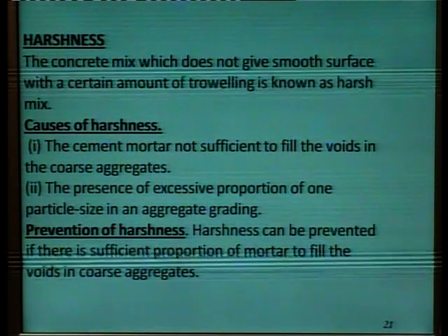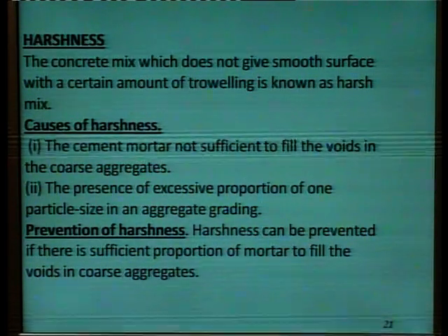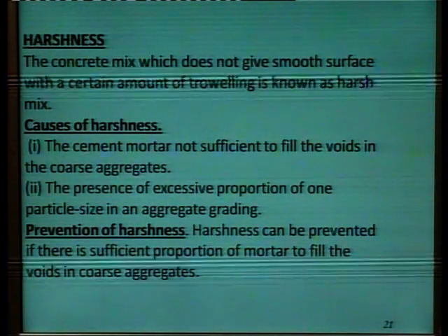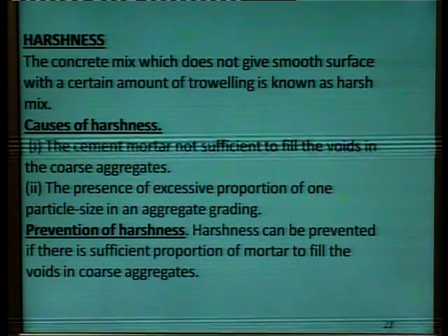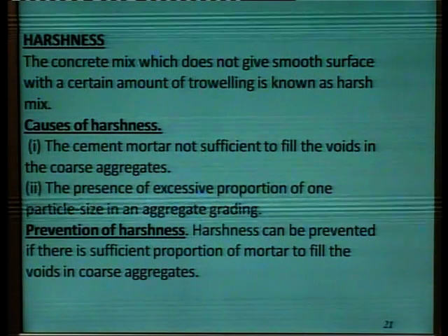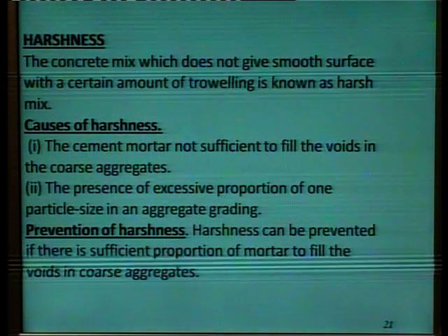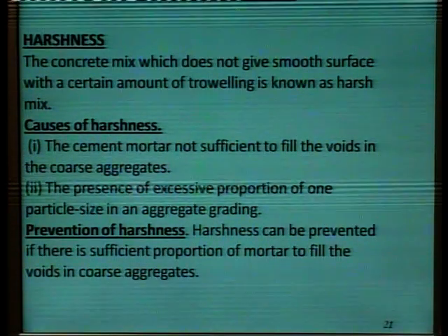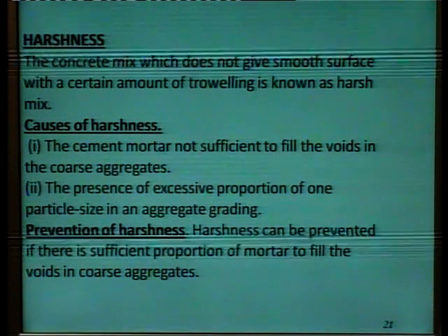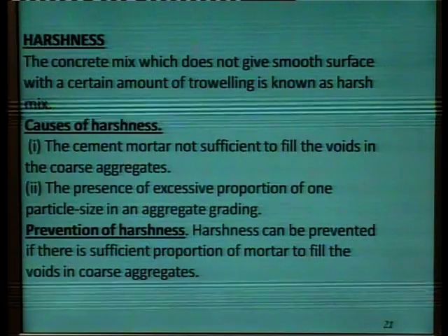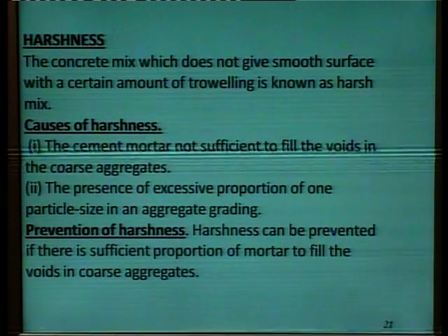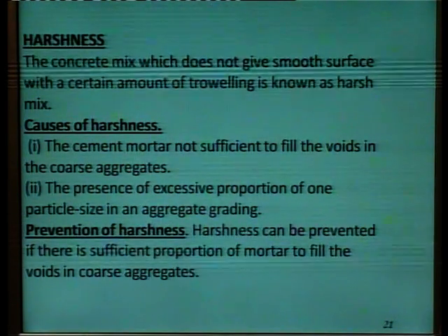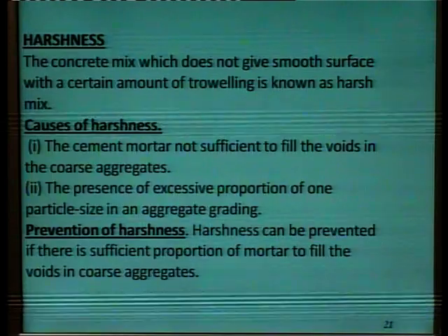Causes of harshness. So, first is, the cement mortar not sufficient to fill the voids in the coarse aggregates. Second, the presence of excessive proportion of one particle size in an aggregate grading.